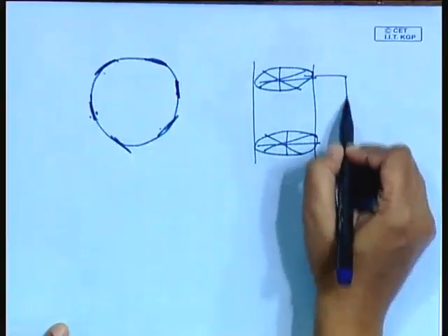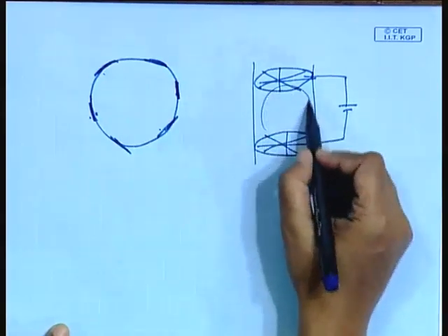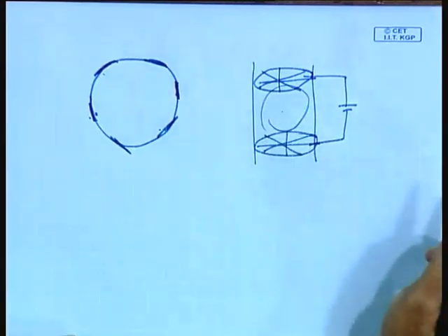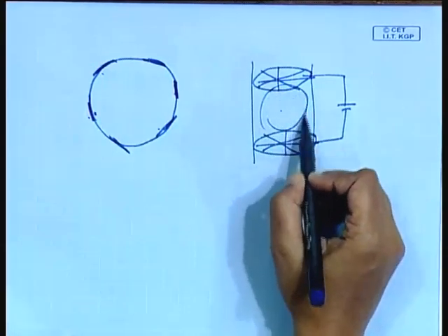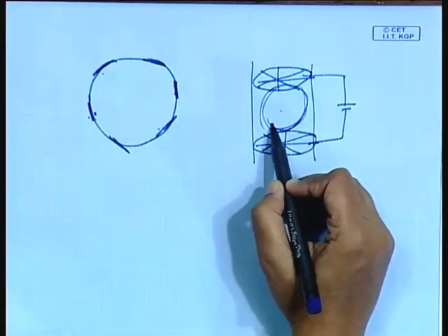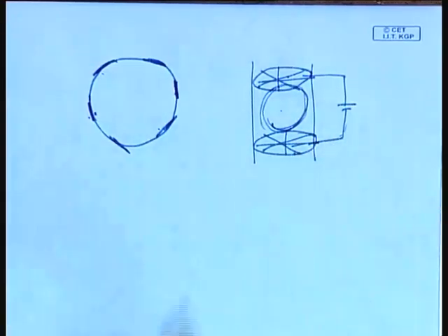We can have those two on both the ends, connected or completed to a circuit. This is usually used for bubbly flow, for measuring bubble velocities, etc. Depending upon the two phase mixture here, we can obtain an idea about the volume average void fraction.